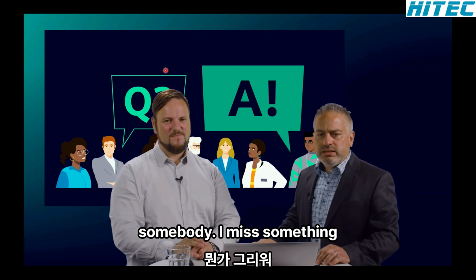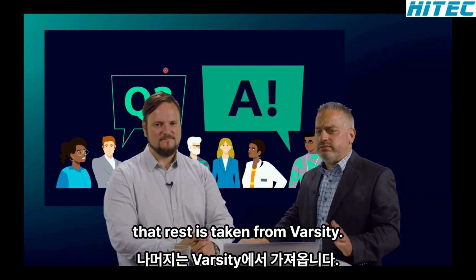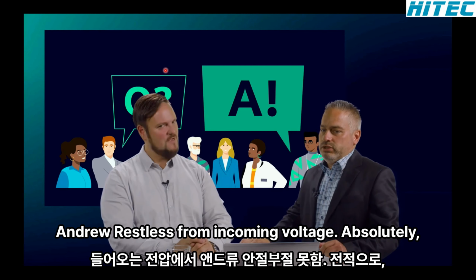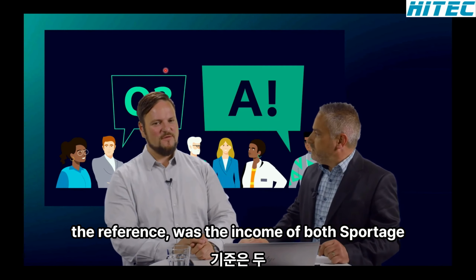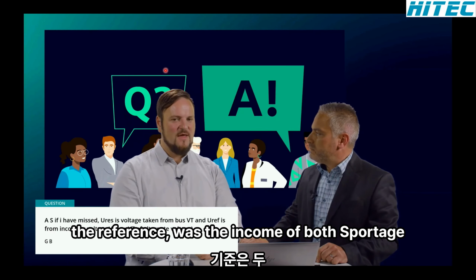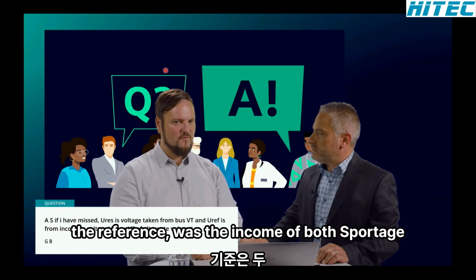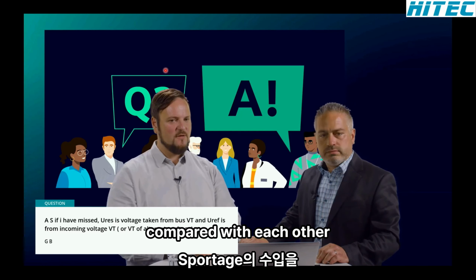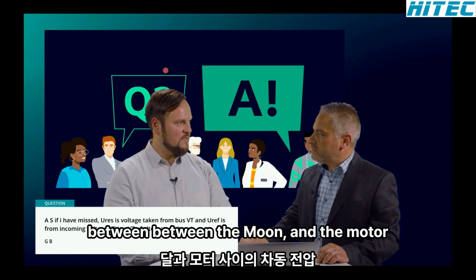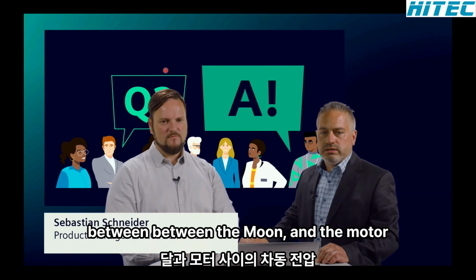Somebody asked if URES is the voltage taken from the bus VT and UREF is from the incoming voltage VT. Absolutely right. The URES is the residual voltage on the motor bus, and the reference voltage is the voltage from the incomer, from the alternative source. Both voltages are compared with each other, so that we calculate the differential voltage between the incomer and the motor. I hope this answers the question.